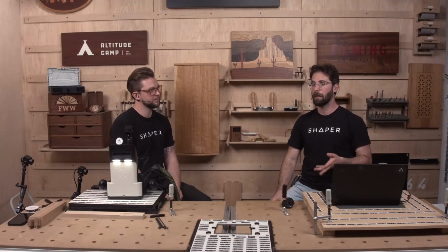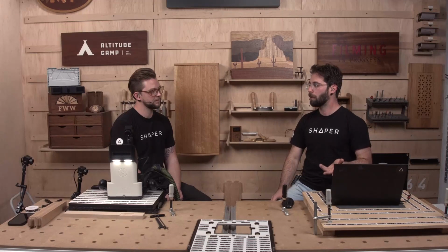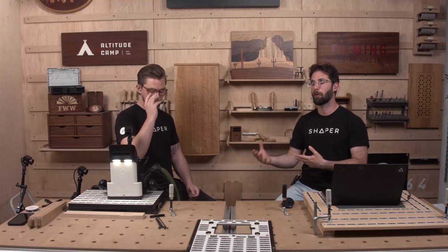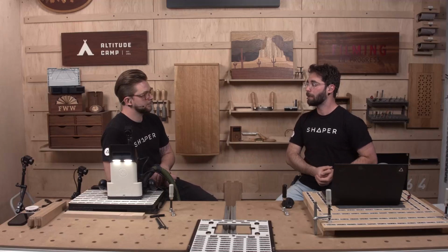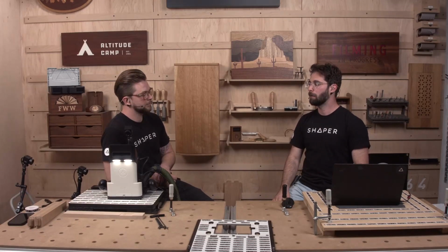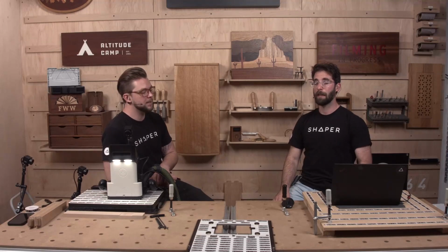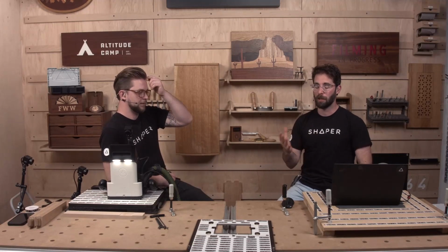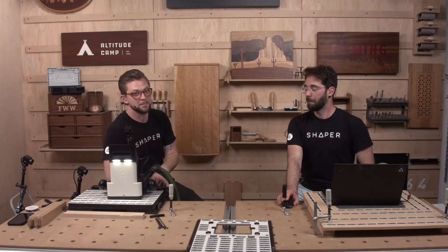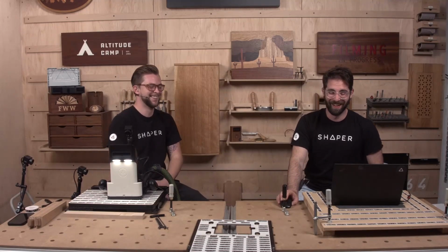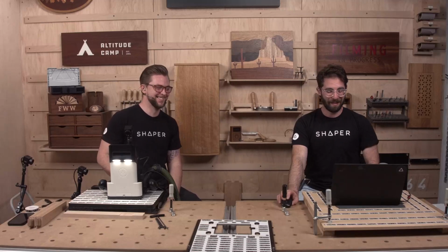One thing we want to get ahead of is if some files have been encoded with a depth of 0, that doesn't necessarily mean that you actually have to cut that at 0 depth. That means that maybe that person just exported a sketch that has 0 depth. There could be a couple of different ways that that happened, but now we've taught you how to edit those encoded depths and save that automatically to your workspace. Yeah. And that's for any creator on ShaperHub, not just us. There are going to be a lot of encoded depth files out there. We've kept Russ really busy by updating every single hardware file with encoded depths, so please use it. Yeah, but it's my pleasure, really.